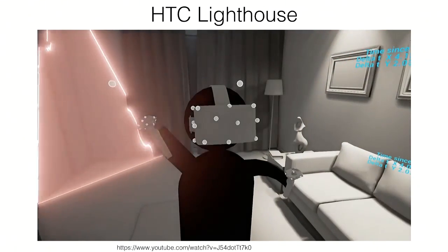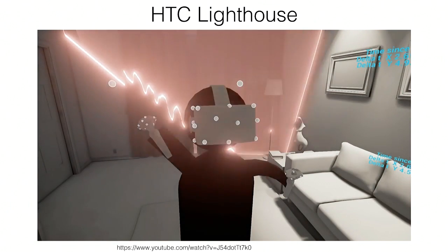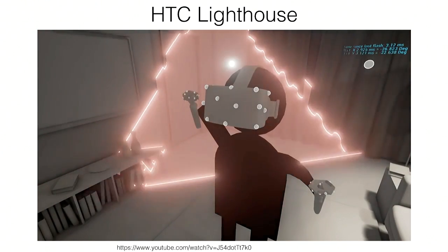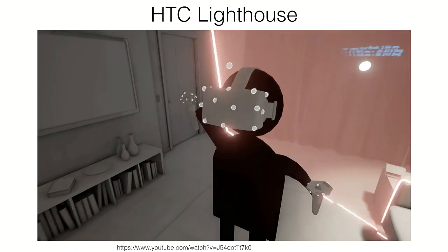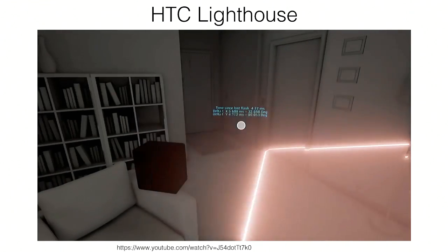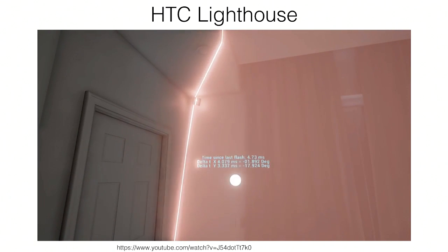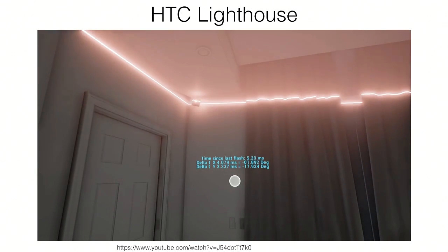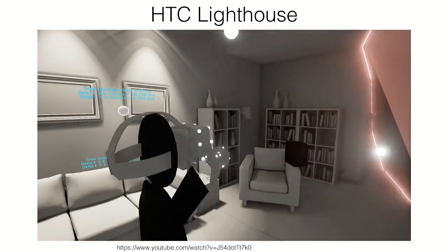And so then the photodiodes know their own 2D XY position with respect to the sync pulse, which you can compute from the time it took from the sync pulse all the way until the sweep hit them. And the difference in that timing is exactly the information that we want to use for the pose estimation. So the benefit of using these photodiodes and the projector is that you can do all the computation locally on the device very fast, and it's time-stamped together with the IMU, right? So you have the same microcontroller, for example, that does the time-stamping of these photodiodes and the IMU readout, so you have the same clock. If you did it on an external computer, then they may be slightly off. So it makes it a little bit easier to fuse the IMU and the photodiodes and so on.